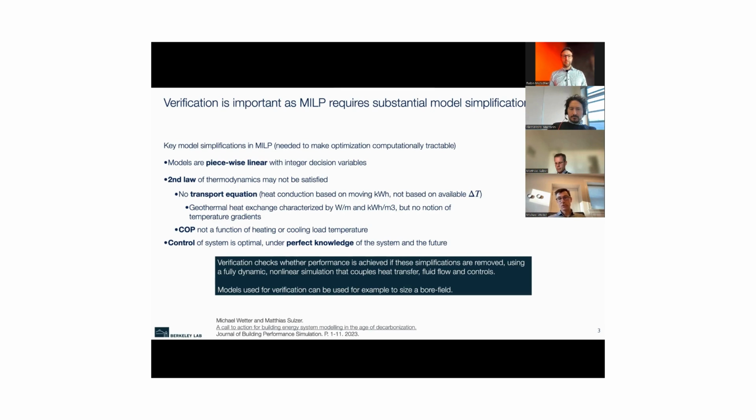And because those simulations that we use for the verifications are much closer to the physics, those models could also be used, for example, to size a bore field, because then at that point we have actual explicit knowledge of temperature gradients that are driving heat transfer into or out of the soil, and also on the limitations in terms of soil temperature that may be achieved because of geological reasons.